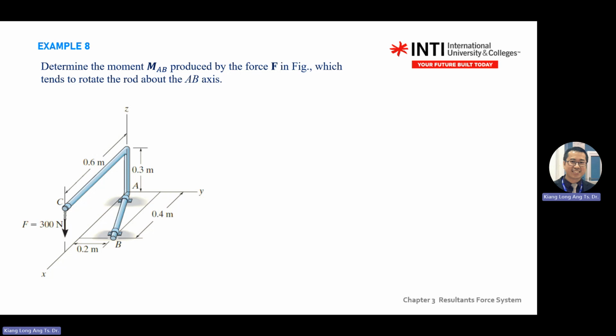Okay, it asks you to focus on this line, this location. So meaning at the end, you're focusing your right hand rule on the AB member. Okay, you can put it on your AB member. So if you're seeing from this direction, AB direction, your direction is anti-clockwise like that. Anything that goes against this one will be negative.